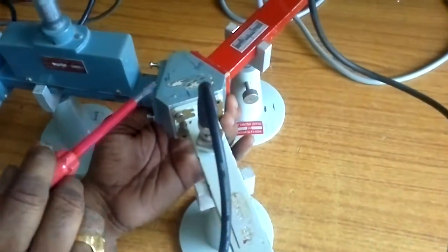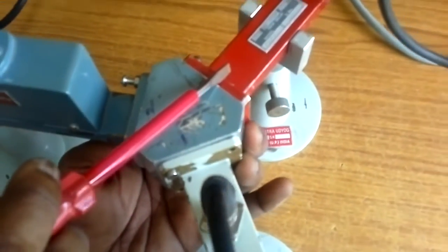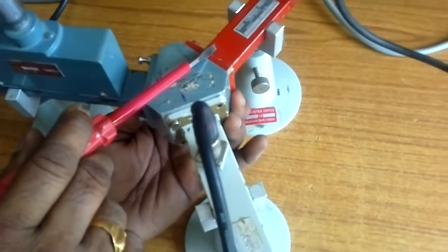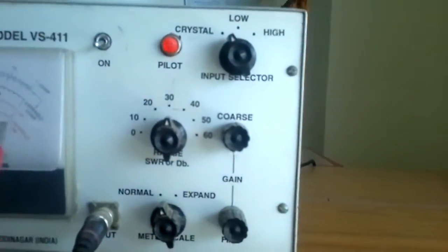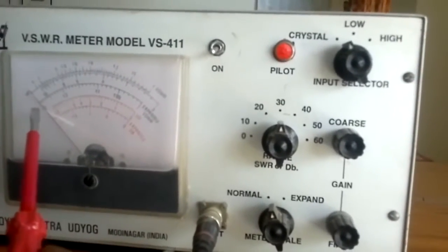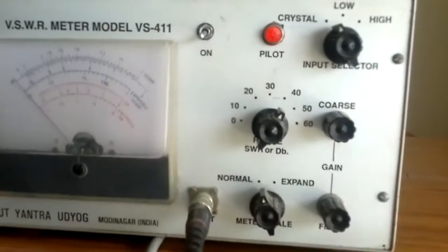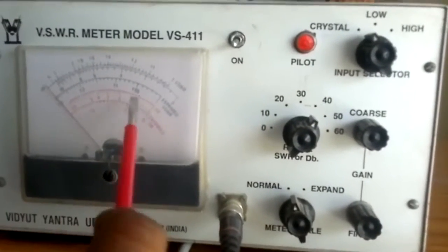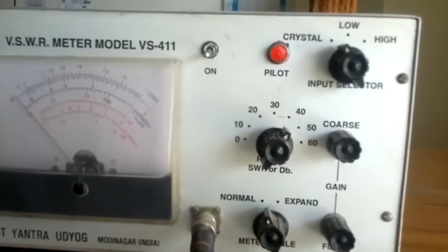See, this is the port 2 as an input, port 1 as an output, port 3 as a matched termination. In ideal condition reading, you see, in 30 dB reference scale, our reading is exceeding more than 10 dB. Now here power is in this scale, it is exceeding more than 10 dB. You go to 40 dB, here also exceeding another 10 dB. That means now it is exceeding minus 20 dB reading.